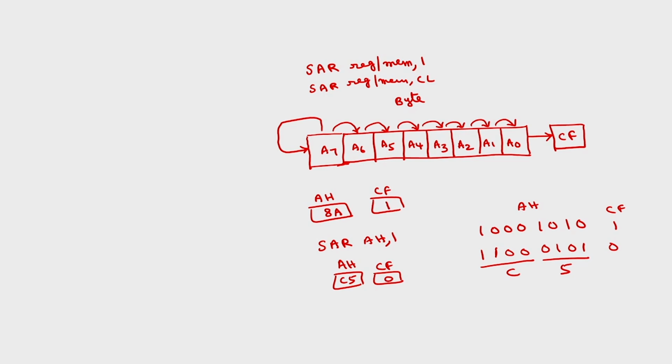Okay. So this is about shift right operation. The only difference is instead of inserting the zeros as in left operation, in shift right operation the same MSB bit will be copied. That is the difference between shift left and shift right operations. So, there are 4 shift operations, 2 shift left, 2 shift right. So, 1 bit position or multiple bit positions. And the last instructions in this group are compare instructions.